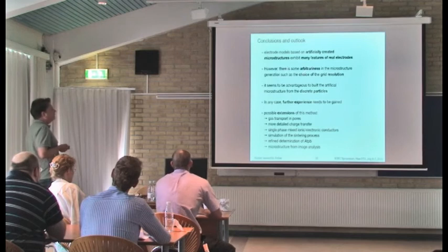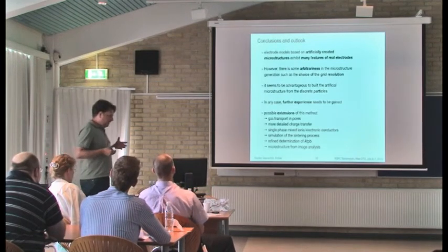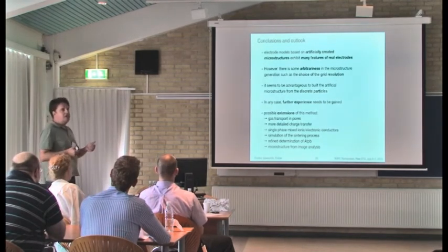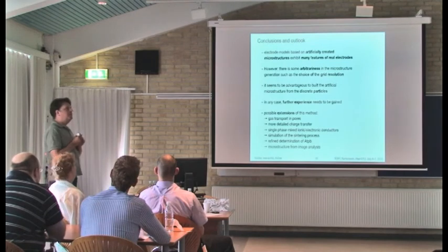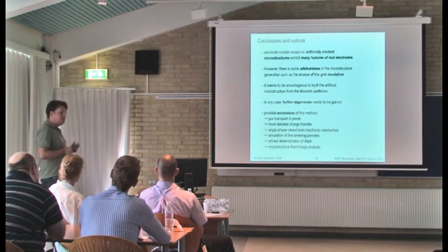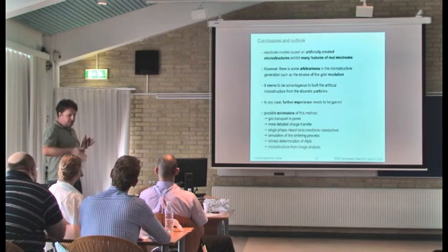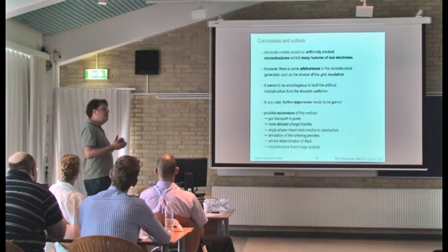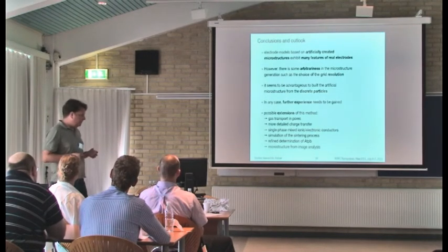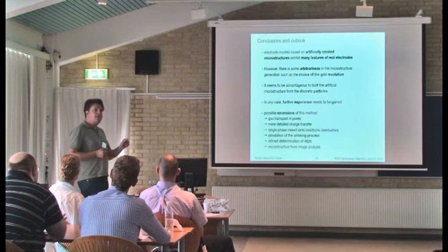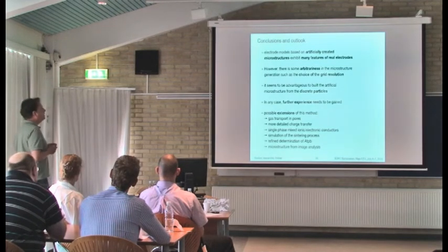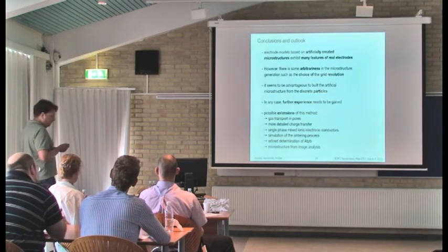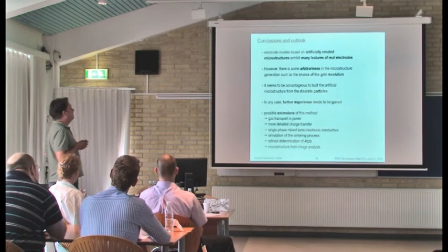However, there's some arbitrariness in that. The particles I have are cubes. This is first of all a limitation. Also the way they can contact with each other. Of course, it's not like in reality, so the cubes are all nicely aligned. There are some ways to overcome that, at least partially, for example, by introducing some effective conductivities at the interfaces between those cubes to account for sinter necks. But yes, this is the beginning, and there's certainly much more work that needs to be done on that.